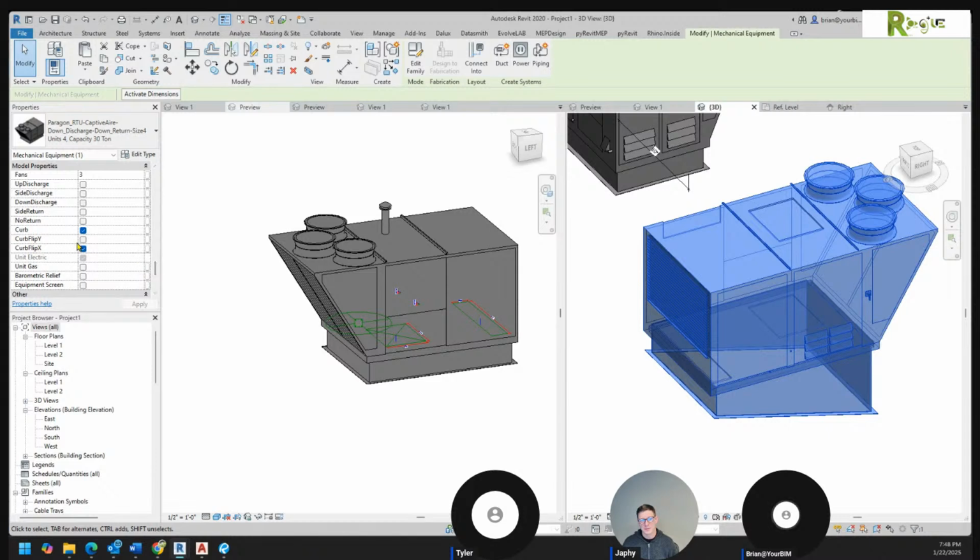But right here, you've got a curb flip. Watch what that allows. See, I can flip that thing from one side to the other. And then this one allows it to go from that direction to the other direction. But believe it or not, there's one slope that you can't go, because with 2 yes/no parameters, you only have 3 options, not 4, the way they've written it. Does that make sense? Pretty slick family.